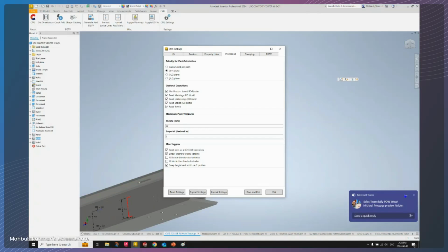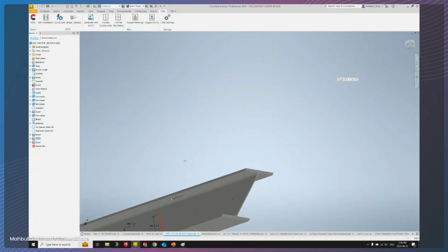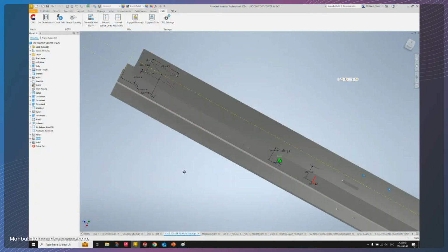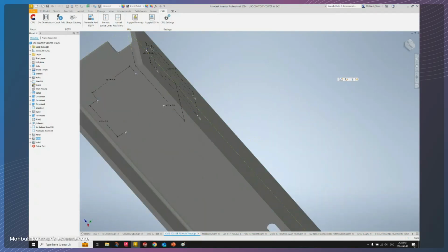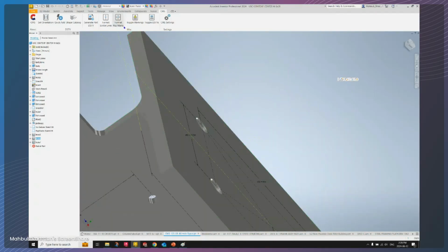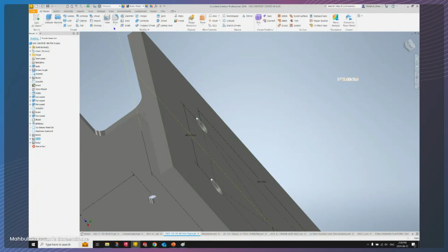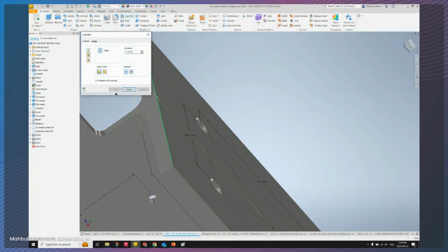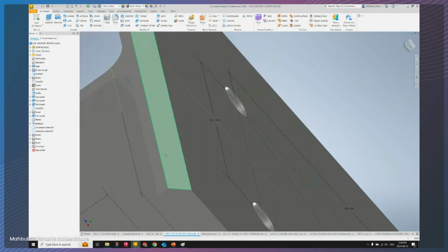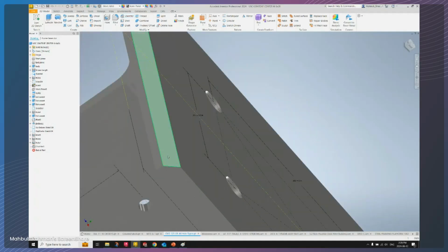not only do you want to do that for those miters, you also want to do that for cases like these. So let's say, for example, I want to apply a chamfer over here on this corner. So let's say I go to the tools, sorry, not the tools, I guess, over here, go to the chamfer, come over here, and say 0.25, for example. So I just added a chamfer or bevel, whatever you want to call it. I want to read that data as well.